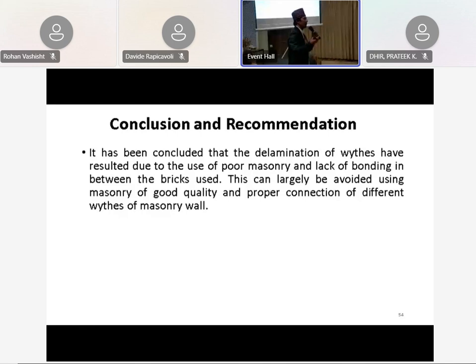Even though we cannot see the micro cracks, in the earthquake it fell, because even in the 1990 earthquake, the same buildings in Bhaktapur did not collapse. But in the recent earthquake in 2015, most of the same buildings collapsed. This is due to the age of the building and deterioration of material, and that is a time factor.